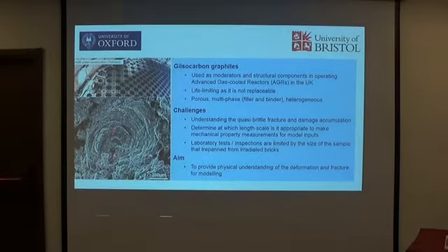If you look at the microstructure, it's porous and has particles. We call them onion-shaped circular particles inside the matrix. It has pores all around, so it's heterogeneous. The challenge is that it's not completely brittle. If it's pure graphite, it's brittle, but this type of graphite, because of the porosity and the particles, is actually quasi-brittle. So we have to decide at which length scale we need to measure the mechanical properties, and how we can feed these measurements into modeling to predict what's going to happen in a real component in the reactor.